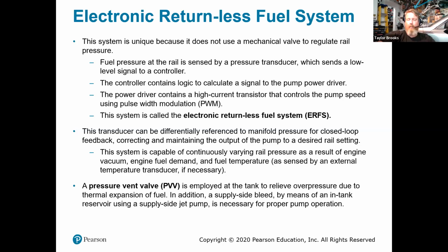Disperse it amongst the fuel that is waiting in the tank, and the process starts all over again. However, you do have to have additional plumbing and additional fixtures inside of the fuel tank, as well as the fuel rail, and so on and so forth. And the regulator has to be mounted externally.